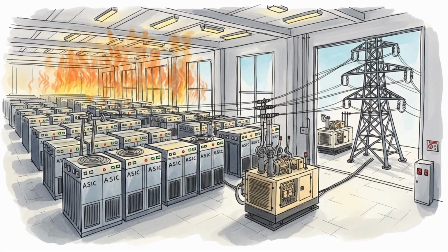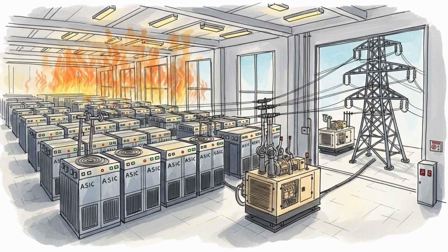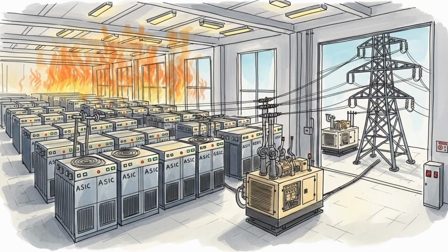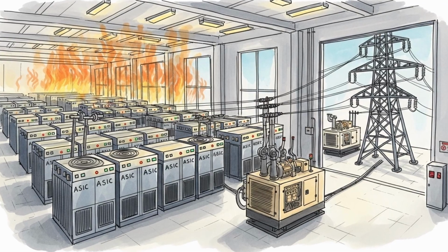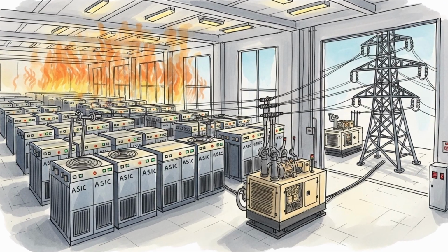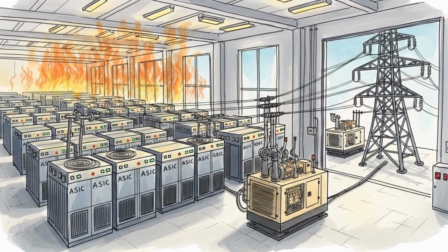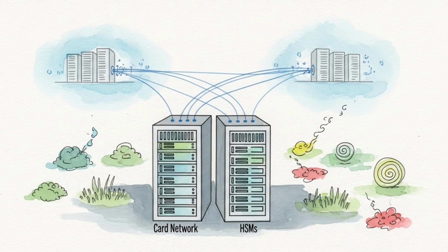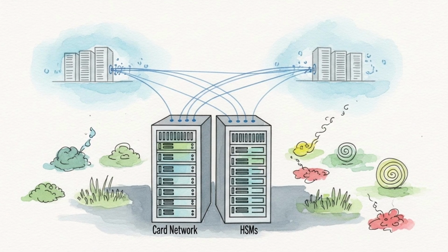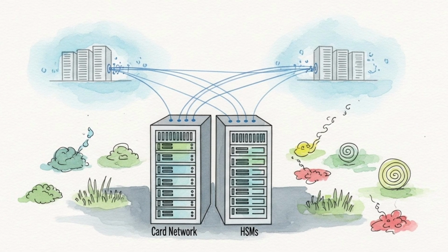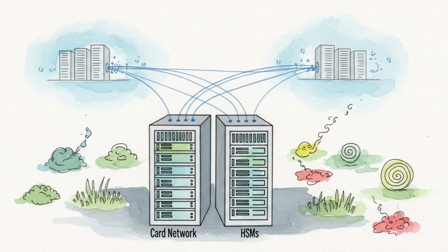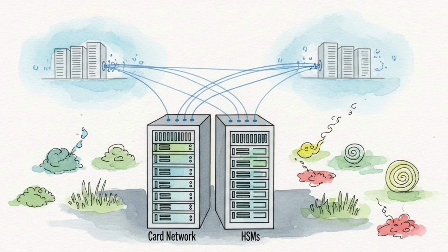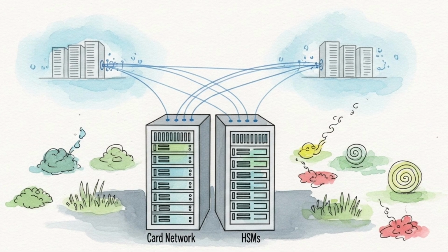In summary, exposure in power systems comes from long conductors and large transformers. The main physical mechanism is direct current bias that causes partial saturation, extra heating, and heavy reactive demand. Monitoring of neutral currents and harmonics, clear operating guides, adequate reactive reserves, and pre-planned topology changes reduce the chance of widespread voltage collapse. Durable hardware choices and a credible spare part program shorten recovery if damage occurs.